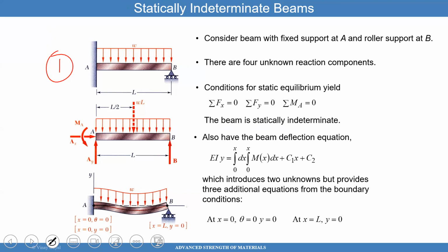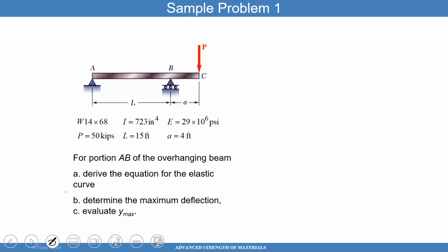If you look here very carefully, you will see that you have multiple boundary conditions and multiple reaction forces, and these equilibrium equations are not enough to solve the problem because you have more unknowns than equations, and so you're kind of stuck. For problems like that, you want to do a very similar integration, which will produce two unknowns, but you have three equations. And what you'll do is enforce those boundary conditions, and I'll give an example on how to do that to solve those kinds of problems.